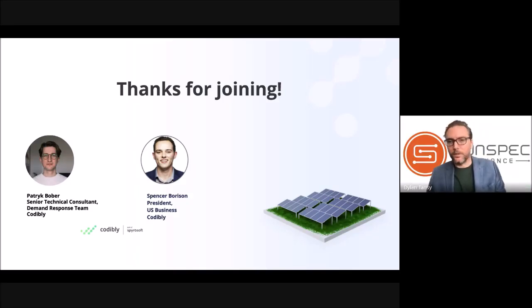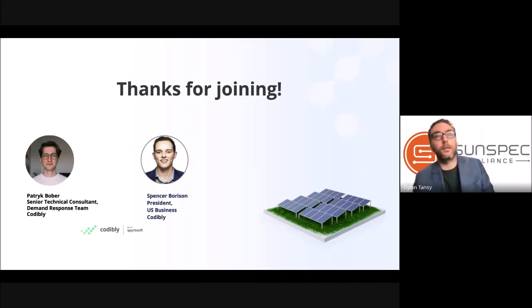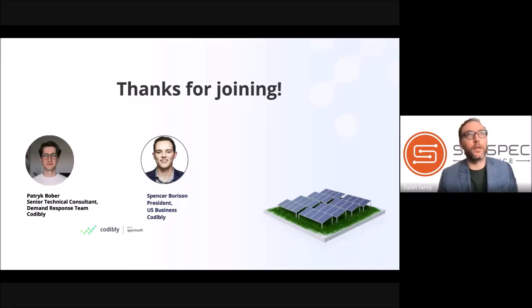Yeah, I can offer a couple comments on this one as well. I haven't heard of utilities standing up their own unique PKIs or roots. There was early on in the CSIP development in the Smart Inverter Working Group, this idea was floated, but in those discussions amongst the industry, it was determined pretty quickly that the requirement to support multiple PKIs for multiple utilities would be extremely burdensome and costly for manufacturers to support. And in addition, once the utilities dug into it and evaluated what it would take to set it up, they determined that most likely they didn't want to take on the associated risk of providing that either.